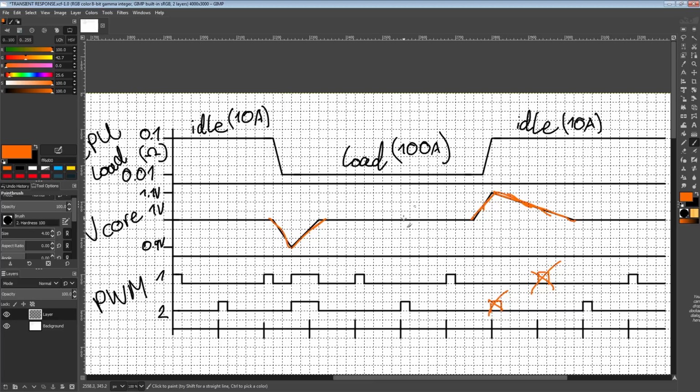You'd basically need to run very edge case overclocks on lots and lots of CPUs, and then some of those CPUs would have to be subject to voltage regulators with bad transient response, and some with good voltage regulators with good transient response. Then you'd have to take the statistics of which ones degraded how much in how much time, and at the end of that, you'd probably find that the VRM with better transient response degrades CPUs slower than the other one, but by how much, I have no idea.